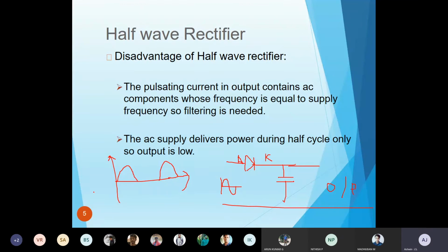Listen. So during the positive half cycle, just consider this quarter cycle. This is actually a full cycle from here to here, and this is the half cycle, and this is a quarter cycle. So during this, I am giving the positive voltage. So in this time period, the capacitor will start to charge. Okay. So initially it is in zero condition, and I'm just saying that it is providing a 5 volt. So from here to the maximum Vmax, the capacitor will start to charge. Now it is having the 5 volt of your AC.